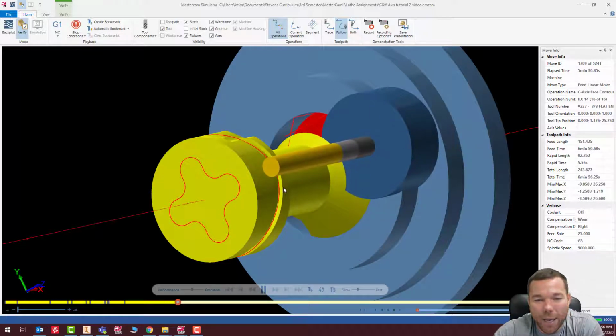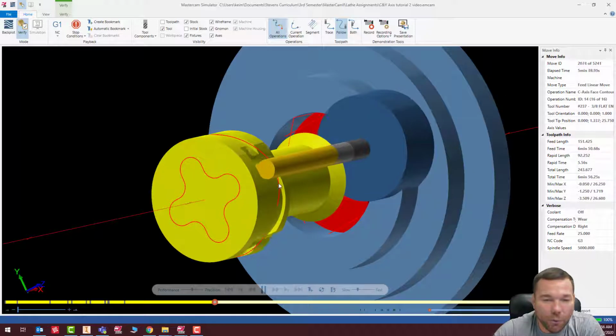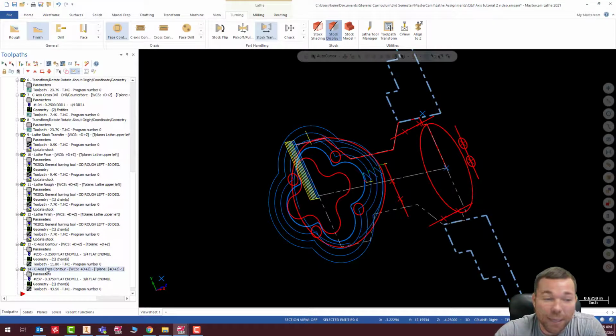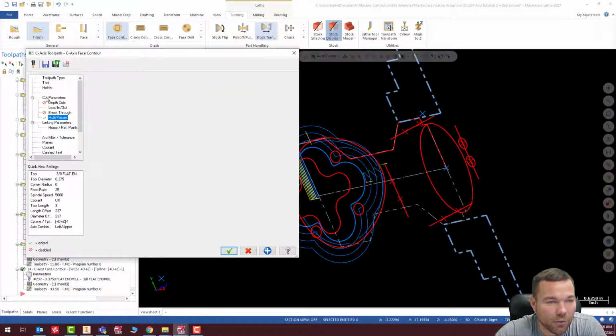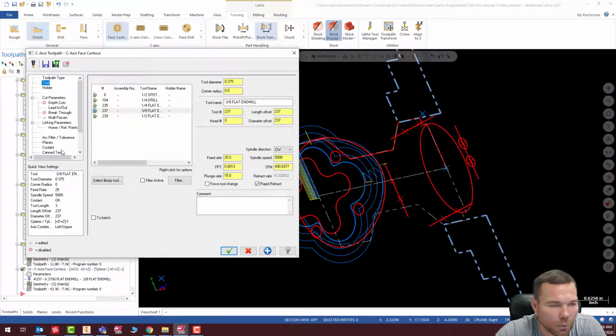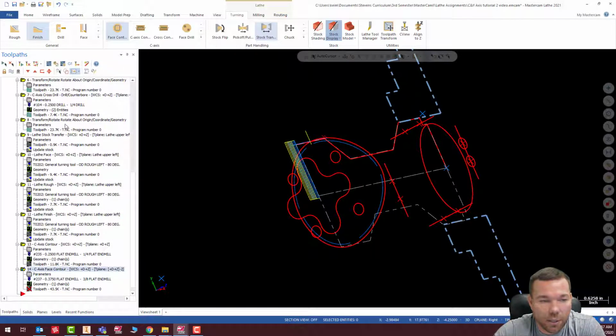Okay, so this is why my cutter comp was bad. What we have to do is flip that around. We didn't pick an axis selection for that. Let's go to, I think it's under our tool, or where is it? Axis control, here we are. So we want right upper, check.